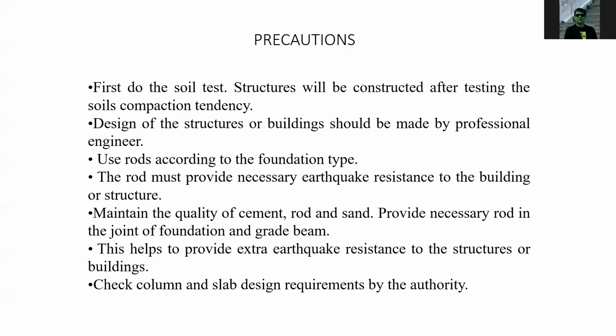If you will be building something more than 2 floors, make sure that you execute a soil test on the ground. Design of the structures or the building should be made by professional engineers. So this is also a better and good way to design something, to hire a professional engineer to design your structure.